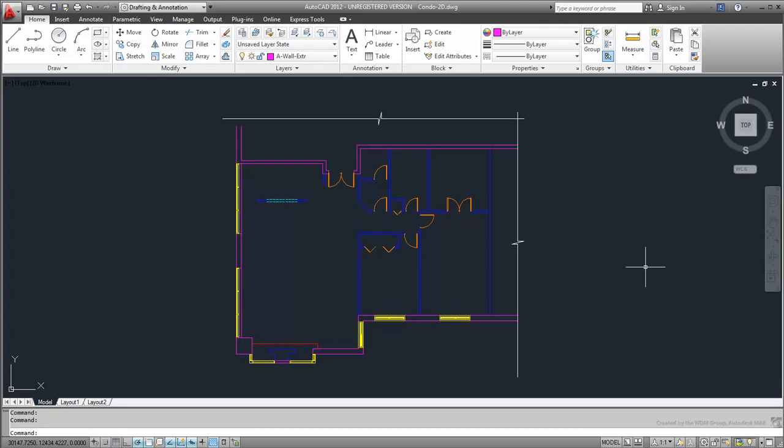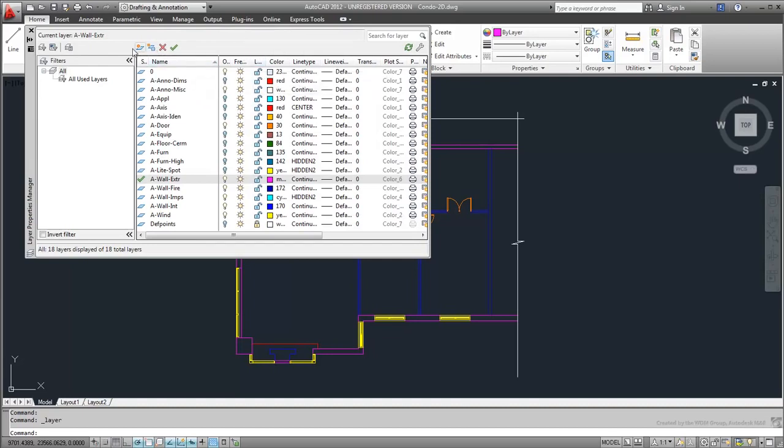Still, here you take a different approach that consists of creating closed polylines that you can easily turn into 3D objects later. In AutoCAD, create 3 new layers named 3D Walls Ext, 3D Walls Int, and 3D Floor. Keep in mind you can create all these layers in one sweep by separating them with commas.